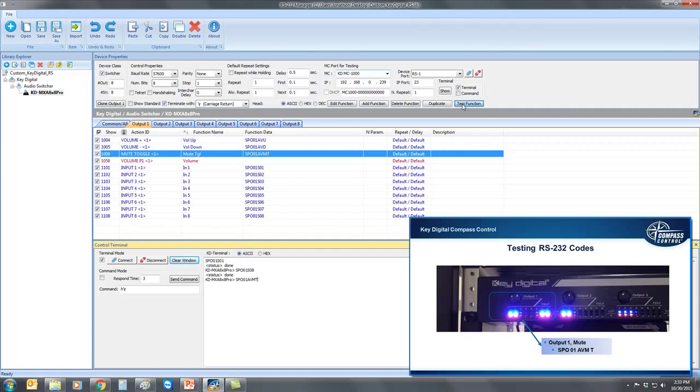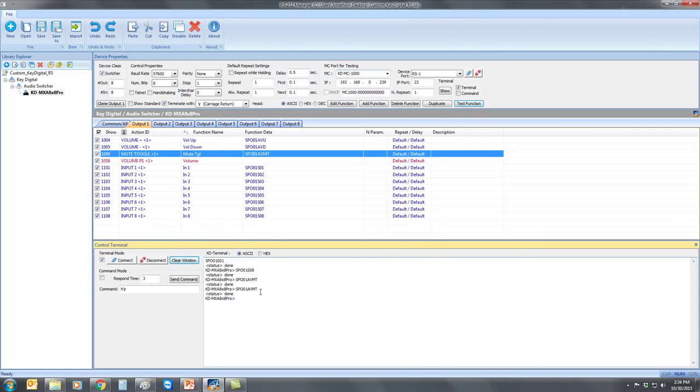So I'll test the mute, and on the face of my MXA, there we are, I get confirmation. It does a nice thing. It shows you 1, 2, 7, and 8 on the LEDs. So the outer bookends are illuminated, so you can look at the face of the matrix and actually see that the volume is muted, in case you thought you had a problem. I toggle that state, and my LED lights return to normal, and it says done, confirming that. So that all makes sense, right?